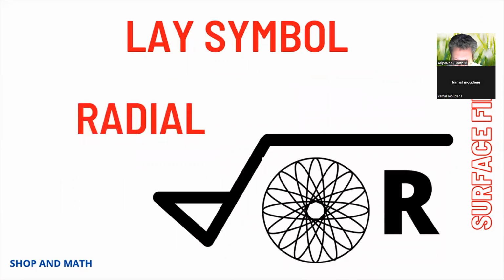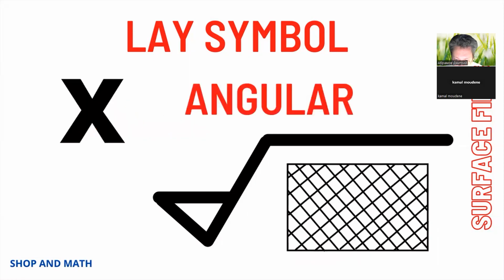Lay symbol radial. Lay approximately radial relative to the center of the surface to which the symbol is applied. A lot of older tradesmen will refer to this as a Blanchard ground symbol. Lay symbol angular. Crossed in two slant directions relative to a plane of projection of the view in which the symbol is used. Basically, it looks like the cross section of a honed cylinder.